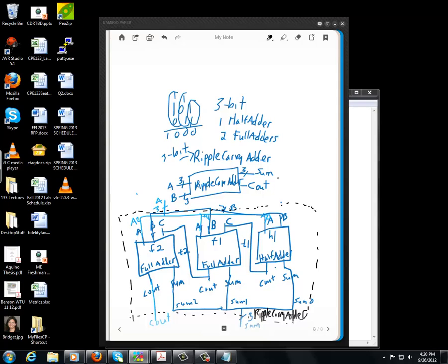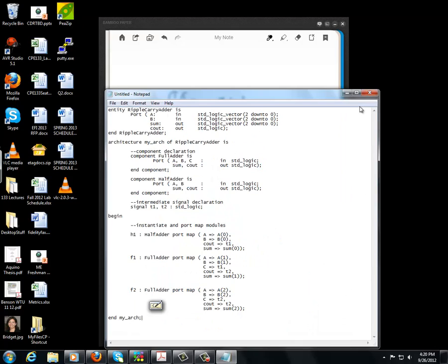So typically your uppermost module, or the biggest black box that contains everything, is going to have all of the signals that connect to the outside world. Everything on the inside doesn't connect to the outside world, doesn't need a separate UCF file. The only thing that needs the UCF file is the outer module that connects to the outside world.